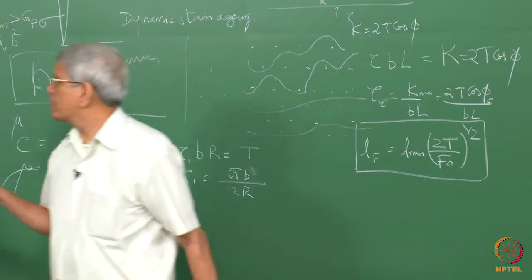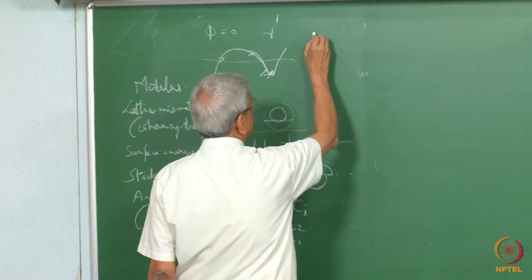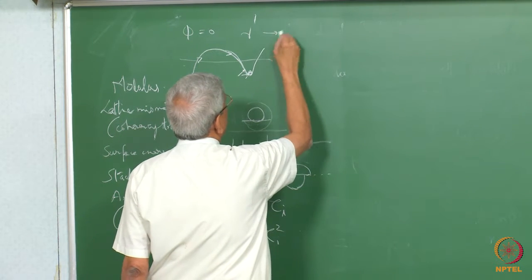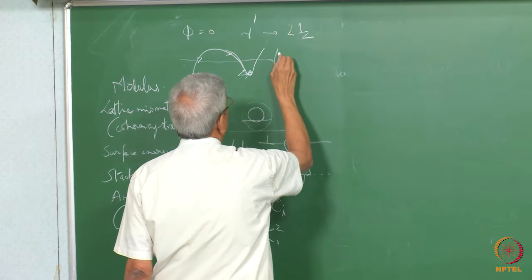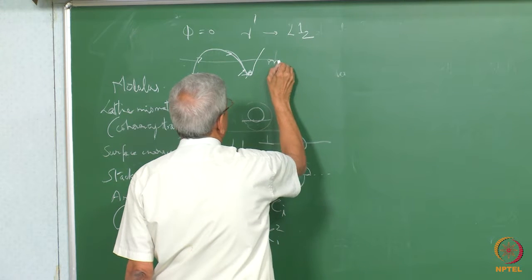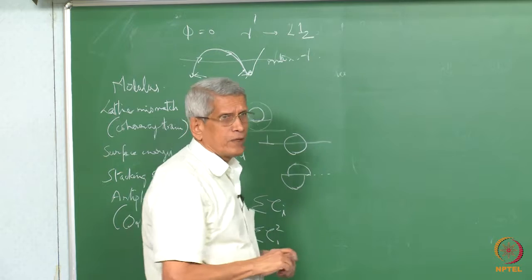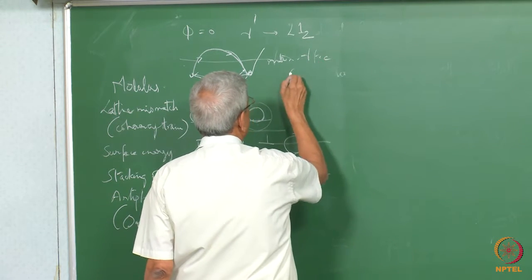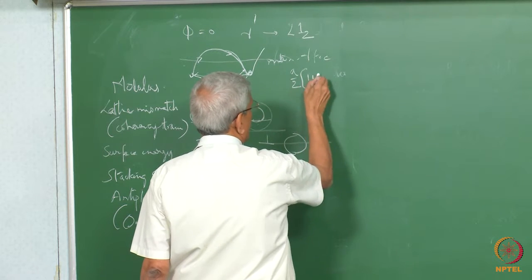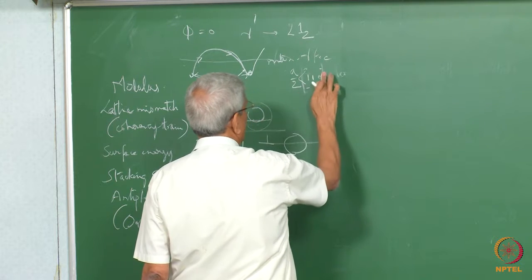In the case of gamma prime precipitation in many nickel based superalloys, the crystal structure of the ordered phase, gamma prime, is L12, and the matrix is gamma. In the FCC matrix, a/2<110> is the Burgers vector of the perfect dislocation.